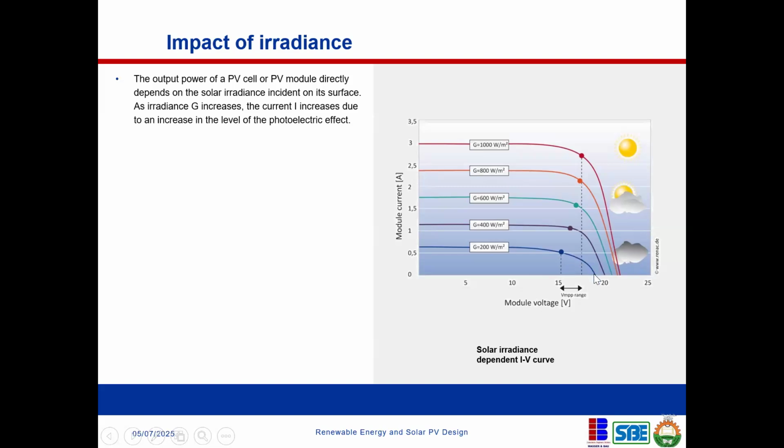See how the voltage has performed. The voltage increased a little bit as the sun is coming out, right? There are two things I want us to know. Once the sun comes out and begins to increase, the voltage will increase slightly. But when I get to the temperature, I'll talk about it. Now let us remain with the irradiance, not the temperature of the sun. Once the irradiance increases, the voltage will also increase, but it will not increase significantly.